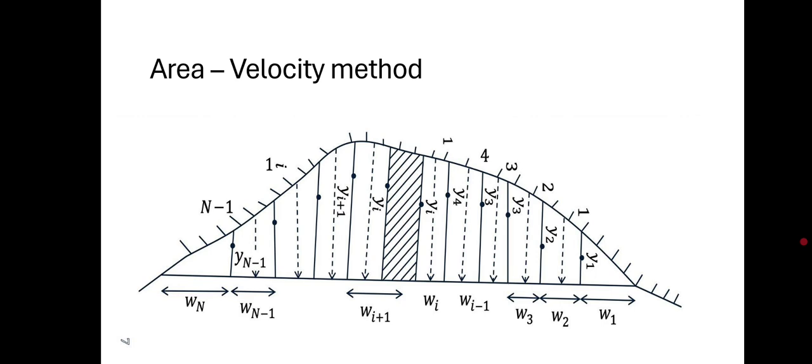To measure the velocity at this point, the current meter is used. The current meter is one of the instruments in hydrometry to measure the velocity at a point in the flow cross section. It consists essentially of a rotating wheel with cone-shaped cups attached to it, which rotates due to the reaction of the stream current with an angular velocity proportional to the stream velocity. Cups get filled with water and turn the wheel when placed in the flowing water.